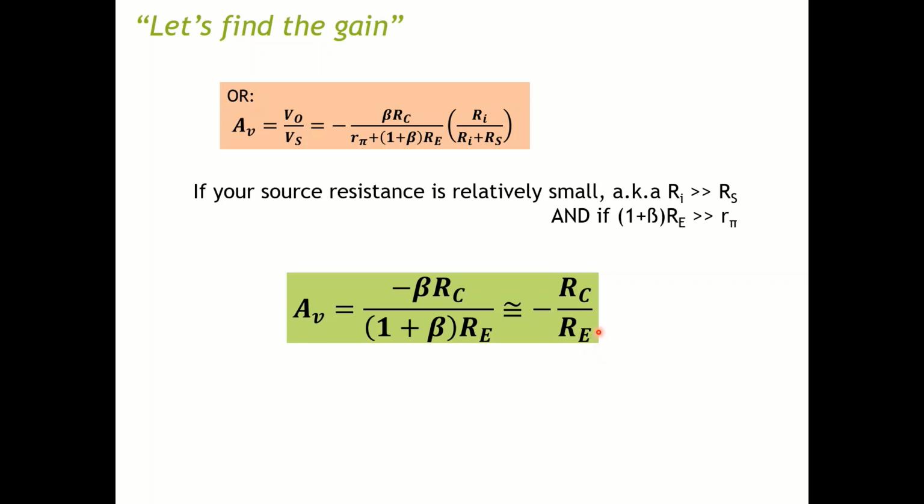So this is a very convenient way to design the gain. These two equations show that the voltage gain for this circuit is less dependent on the current gain beta, in that there is a smaller change in voltage gain when the transistor current gain changes. So you, the circuit designer, now have more control in the design of the voltage gain. But this advantage also comes at the expense of a smaller gain.